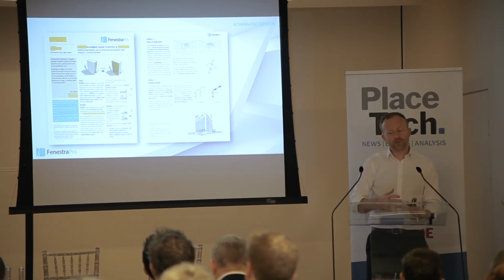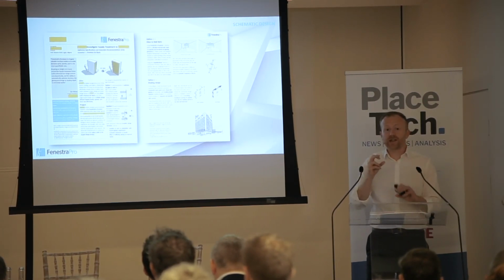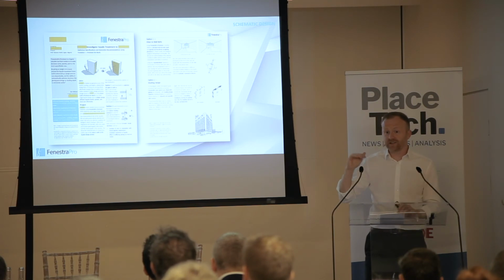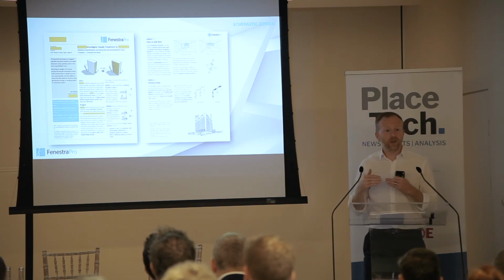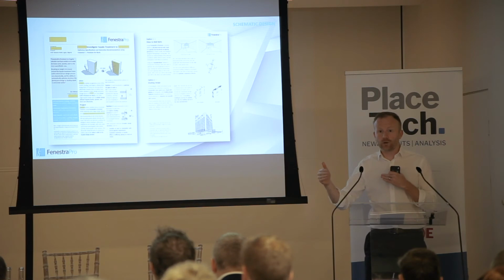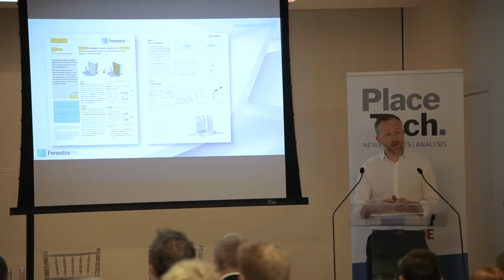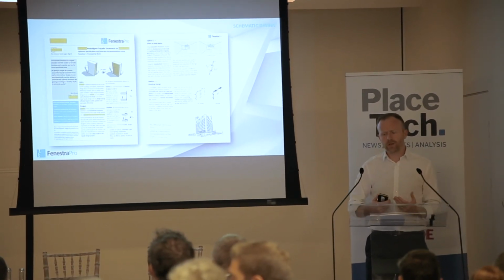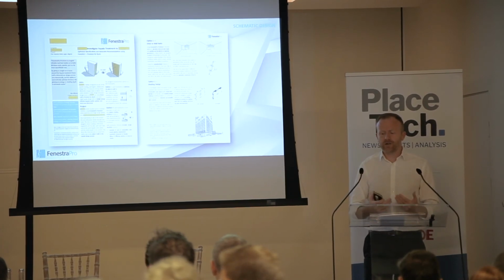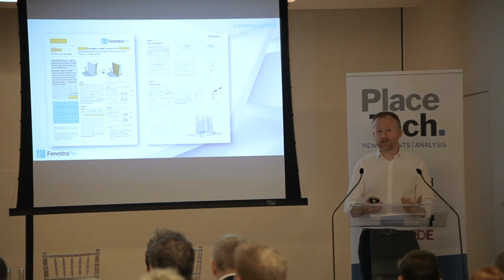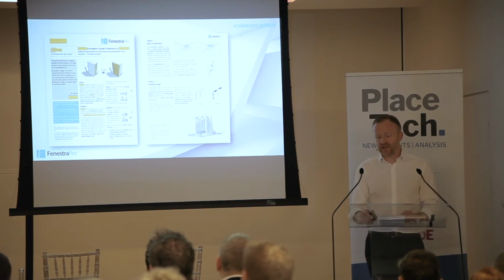But then they did another option where they fixed 40% glazing across all of their orientations, and they used their balconies within FenestraPro as shading devices to shade those spaces. In other words, they had deeper balconies to one orientation, slightly less deep to another, which led them to have more premier rooms or different types of spaces. It was an interesting case study in that they very much allowed the facade to drive some of the internal spaces and the energy performance to make some of their decisions.